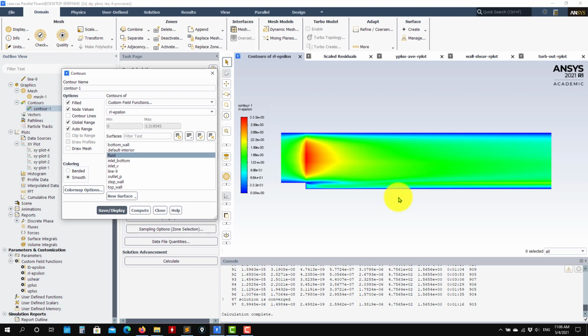But here also this is a good indication now, because usually when you go to scale resolving simulations, you run what is known as a precursor simulation, get an initial solution, and usually it's a good idea to have those values, okay, when you are in here.